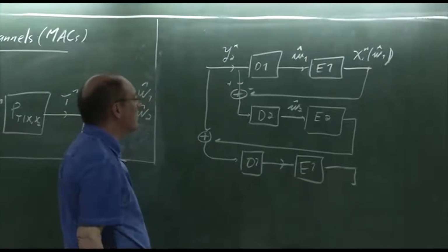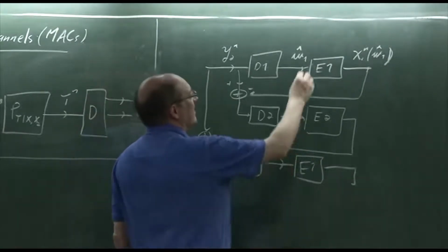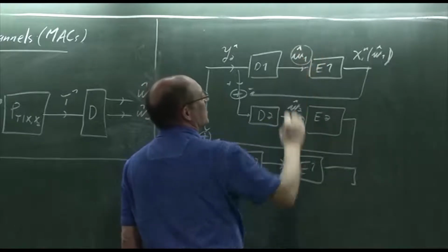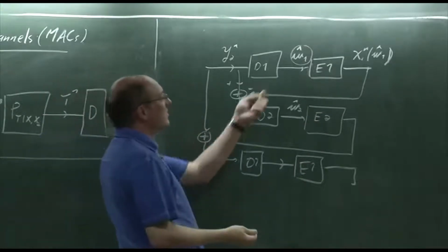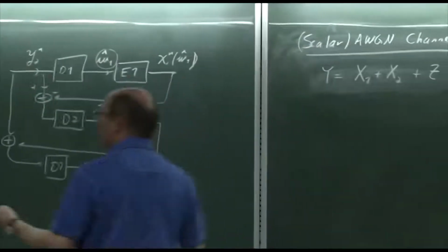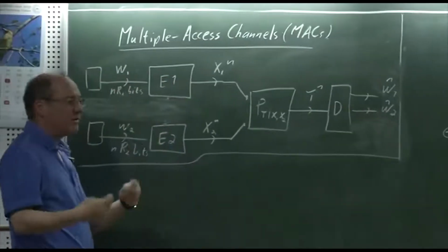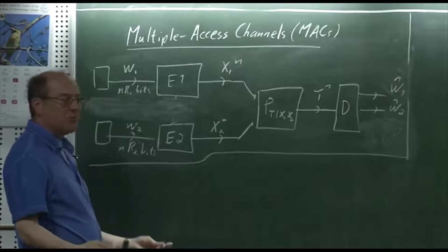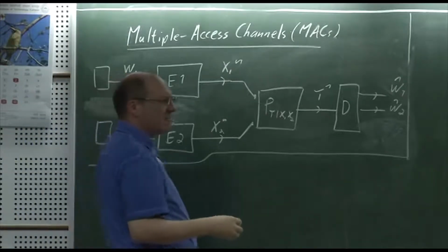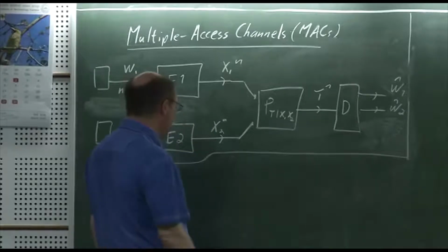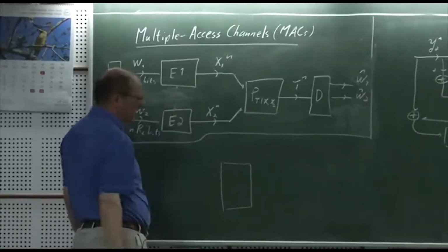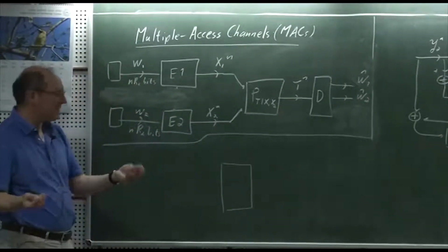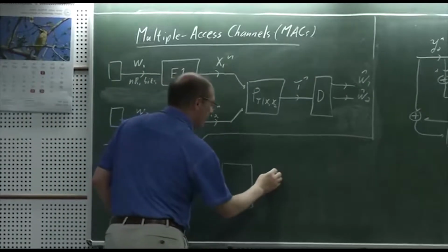One possible reason for doing this is that you might be choosing log likelihood ratios here. Now, in this case, it's sort of hidden through the encoder, but still, you could do this if these were bits. So, for example, just to draw a diagram, suppose both codes were low density parity check codes, and suppose we're using binary phase shift keying. Usually, low density parity check codes are built as repeat accumulate codes. But in any case, let me just draw it in this following form.